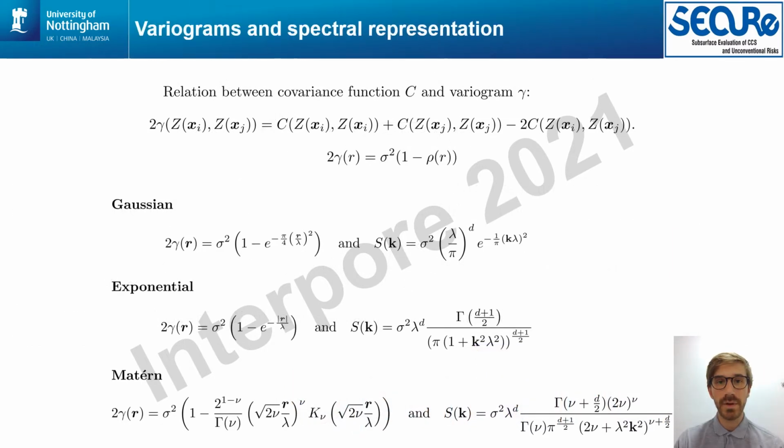The random field library offers three main covariance types: Gaussian, exponential, and Matern. We provide the spectral form S(k) of these variograms because of the method we used to implement the random field generation in OpenFOAM. Other variograms and covariances can be implemented simply by adding their spectral density.